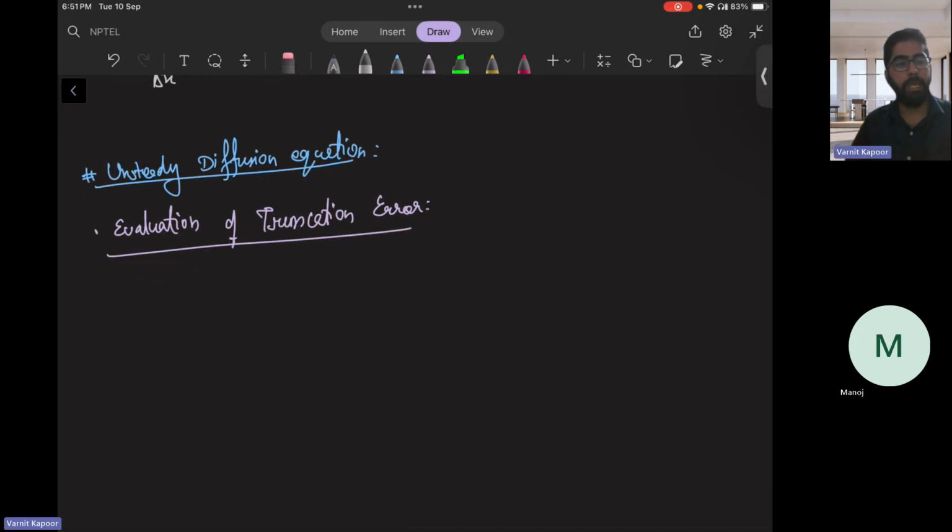So here rho phi p, because it's unsteady, at the next time step and the original, previous time step: phi p naught, phi p1 and phi p1 naught. That is t plus delta t and t, represented by cell-centered values. Then again the source term was also taken to be of cell-centered values. Gamma grad phi was face-centered values, which you took during the assumptions. Then for the source term and gamma grad phi, the values at t plus delta t prevail over the entire time step. These are the assumptions which you dealt with earlier as well, but that was for steady and this is for unsteady.